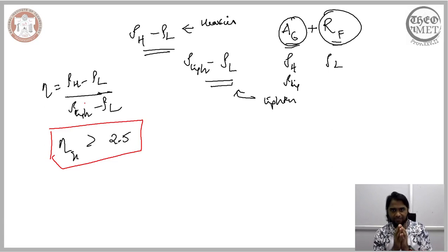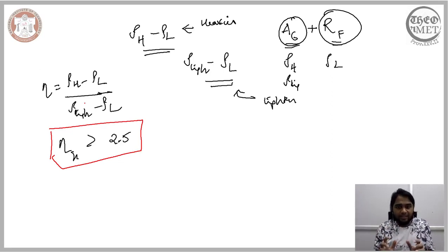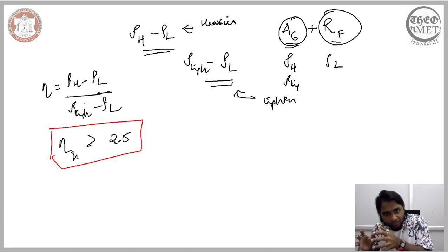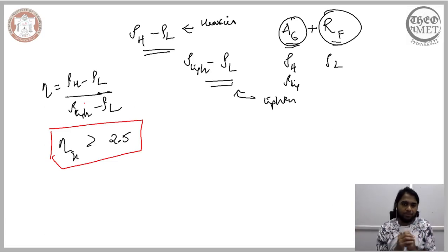Now what essentially we have seen is a way of quantifying the gravity separation, or we now have an expression that quantifies the efficiency of the gravity separation process, and it helps us select reasonably which mixture of particles can be treated using the gravity separation process. So this expression here serves two purposes. One, it helps us understand the efficiency of a gravity separation process, and it also helps us make a reasonable choice of a given mixture to be handled through the gravity separation process.